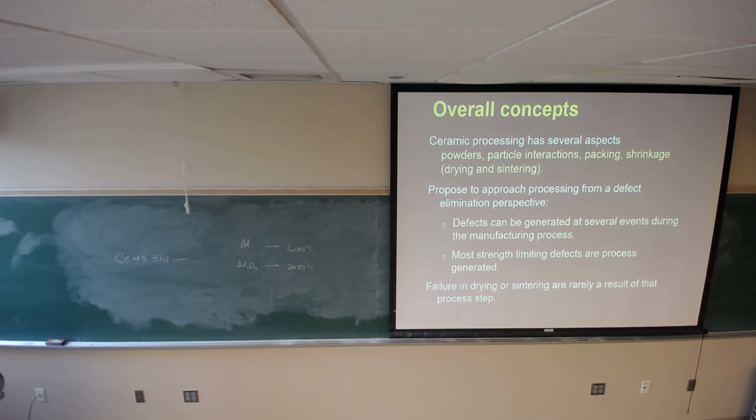In fact, the strength that you measure at the end represents the flaws that you introduced in the beginning. That concept is really important because it drives home the idea that these materials and the defects that you generate are formed in the process, and they're not eliminated in sintering. So that's why we do that. We start with mechanical properties, and then we go into powder characterization because everything we do starts with powders. How do you measure the properties of the powders, and how does that impact the process? So we do that. Then we get into colloidal behavior, defect generation, etc.